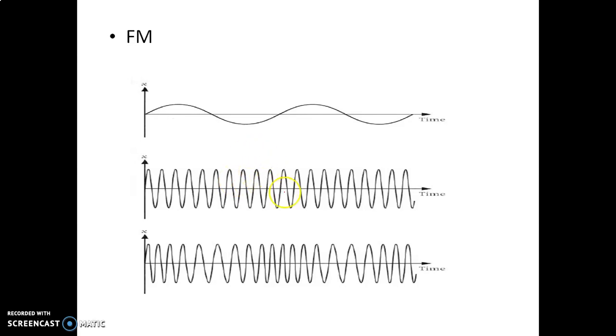When the information voltage, in this we are transmitting the message signal, reaches its maximum value, then the change in frequency of the carrier will also have reached its maximum deviation above the nominal value. Similarly, when the information reaches a minimum, the carrier will be at its lowest frequency below the nominal carrier frequency value. When the information signal is 0, no deviation of the carrier will occur.